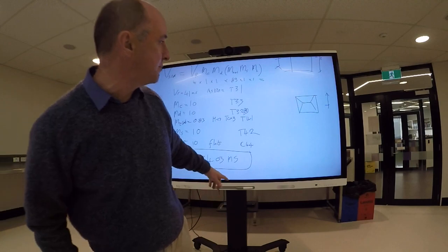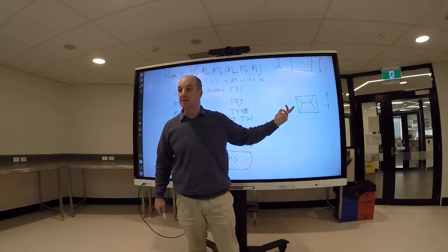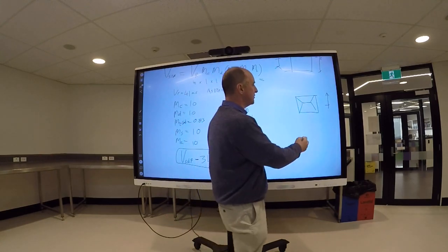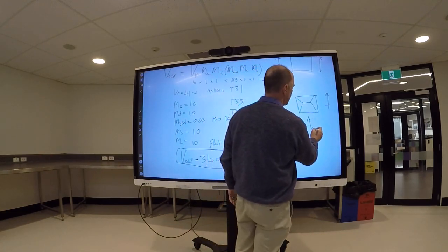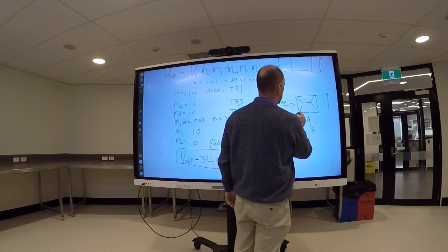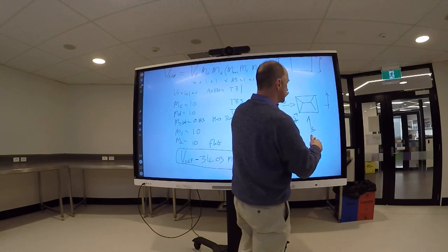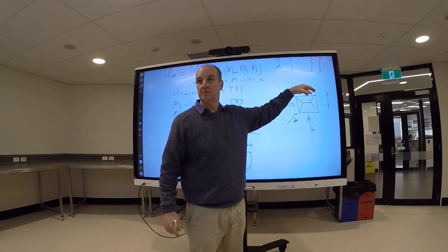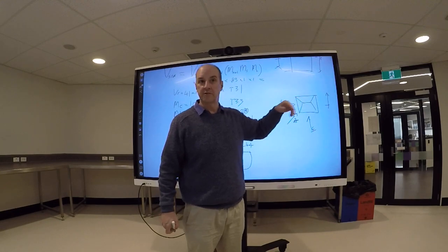If you've got a fairly complex building, you'll end up with 8 wind speeds for the 4 directions and then the 45-degree angles. So you might have a diagram like this, where that is 41, that is 40, this one is 38, and so on all the way around. And then you have to work out the actions from all those different directions.